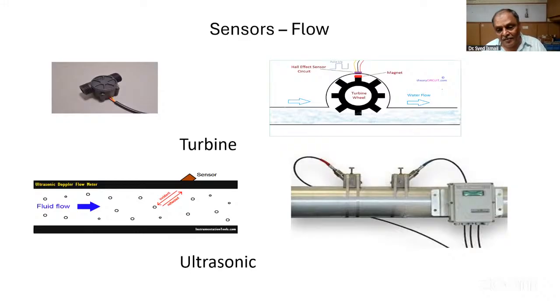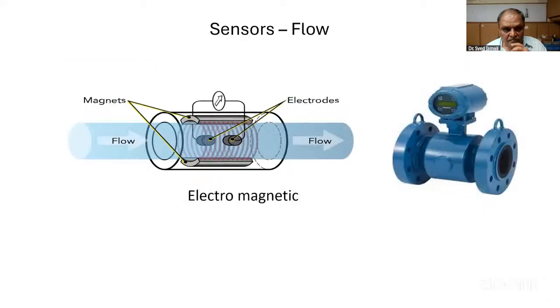The ultrasonic flow sensor is available. For example, it is used for energy measurement, oil movement measurement, gas movement measurement. They are slightly expensive, but in agriculture we seldom use any flow meter. I think this is something that has to be thought about. It can really be done easily. Some institute must work on flow measurement, because we use water, nutrients, everything. Flow measurement is absolutely a must. What is available in industry is expensive, and that accuracy is not required for agriculture.